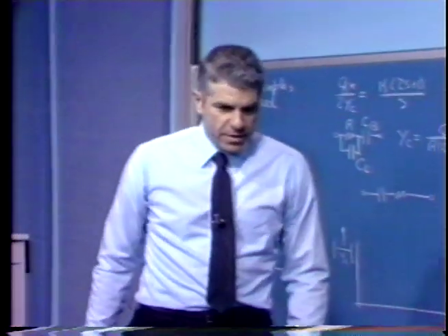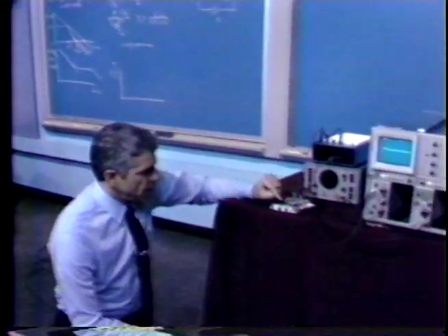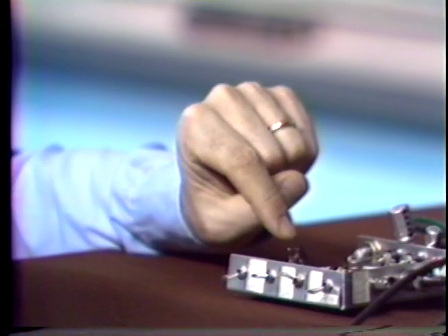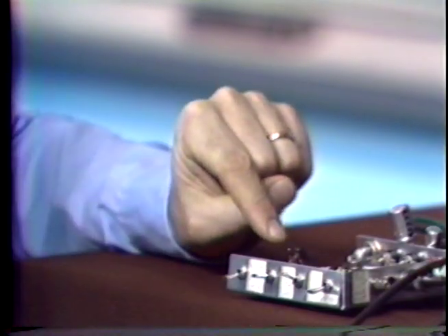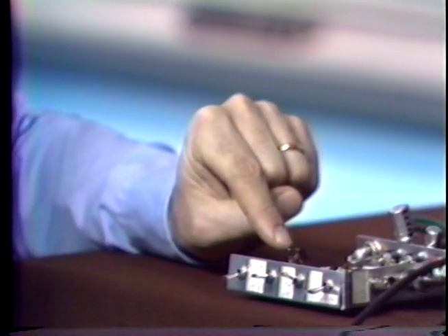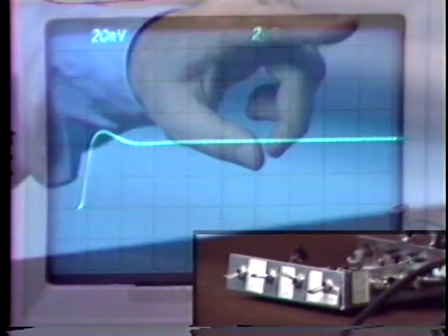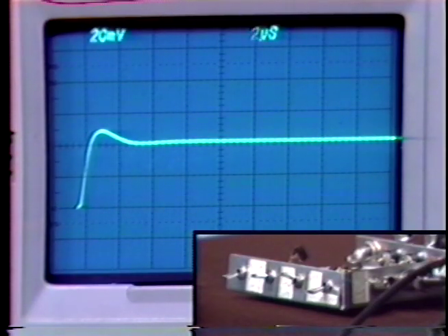And in this particular setup, we've chosen our small capacitor here to be roughly 1/10 of the value of the big capacitor, and that results in a very good compromise between maintaining stability in the minor loop and yet not compromising the stability of the overall loop. So let's now add that capacitor. When we do that, we notice the basic transient response remains the same. We have about the 20% overshoot or thereabouts, but the teeth have completely gone away.